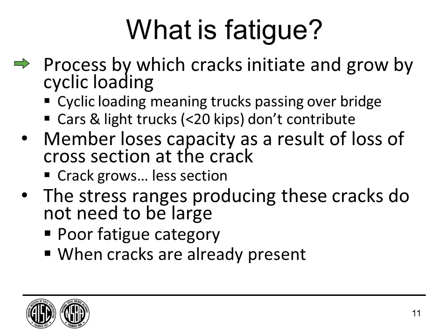In strength design, as was already covered, that's a one-time event. Fatigue is different, right? This is the day-to-day vehicles crossing a structure. It was talked about earlier in the sessions, but there is a specific load that we use for fatigue design. In that load, the way it was developed, we don't include the effects of cars or light pickup trucks. Simply that's because they don't contribute to stress ranges that would cause fatigue damage. In other words, they're very light. It's really trucks that are the damage we worry about.